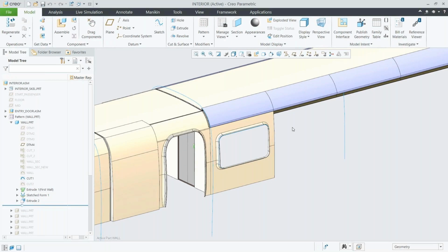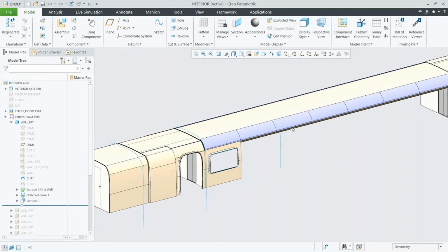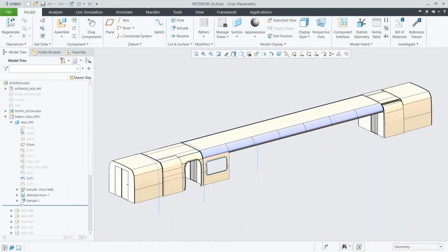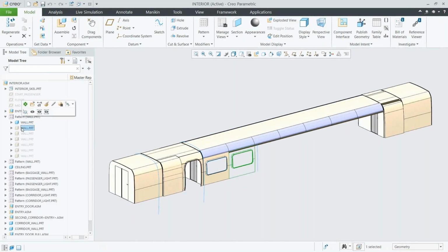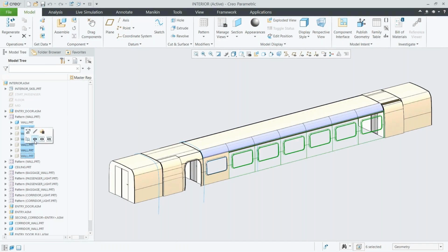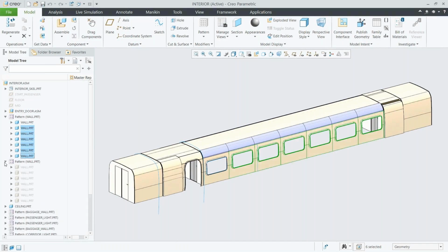So now if for some reason you make a change, say, I want the exterior to bump out a little bit, that window cut will bump out as well, so that it'll always come right up to the end. So the depth of the window and the shape of the window can now be changed from the top level. You don't have a ton of references going everywhere.